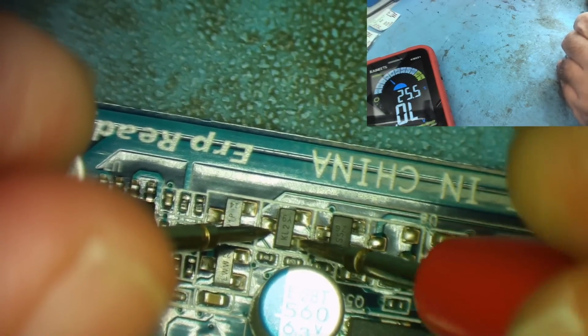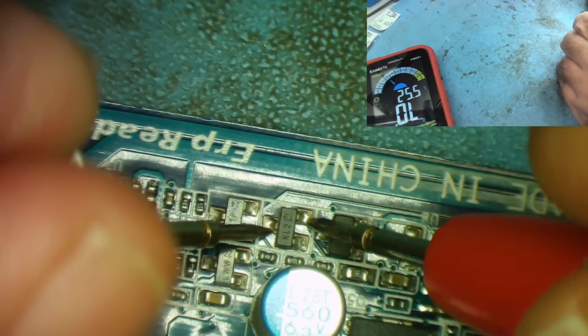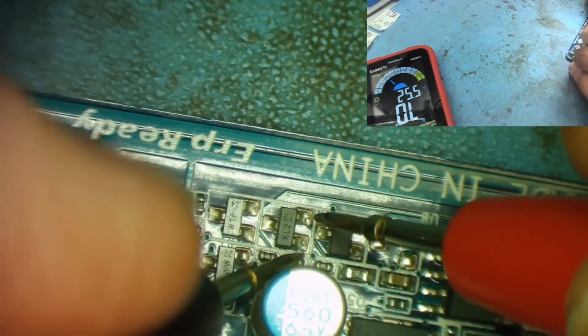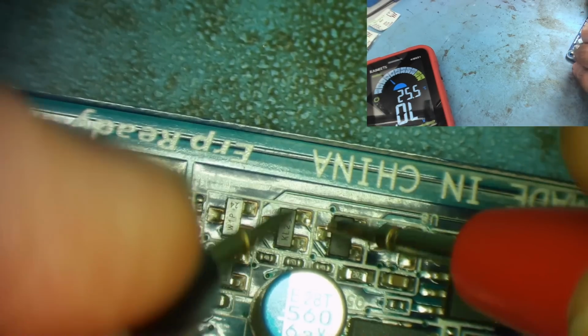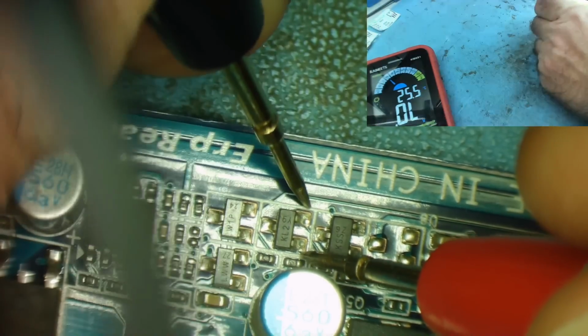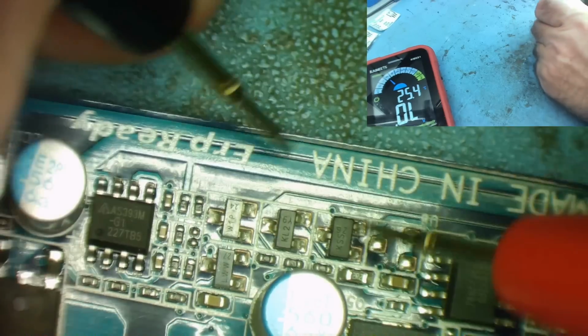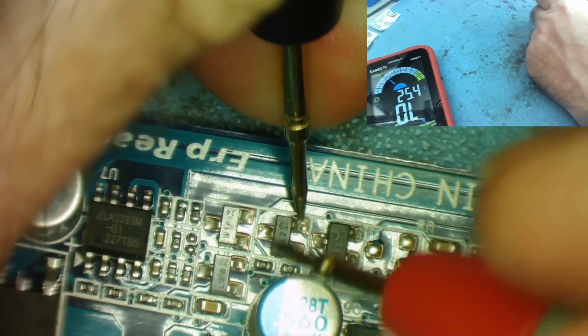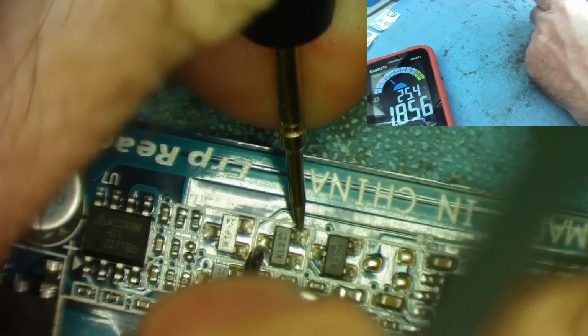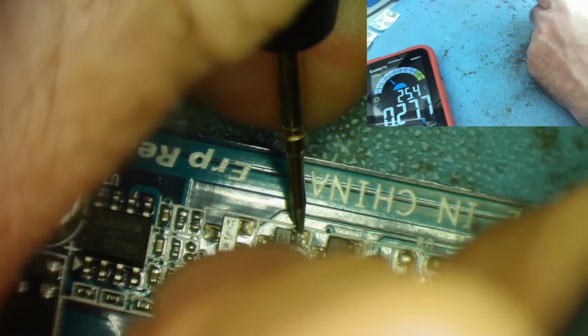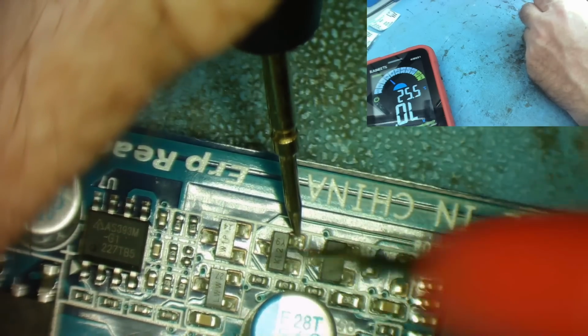This would be the base or gate on the red pin. Nothing there, nothing there. Go the opposite way, nothing there, nothing there between these two. Do we see a diode junction the other way? Yes. So that one I think we can say is a MOSFET because all we can see is the diode junction in one direction.